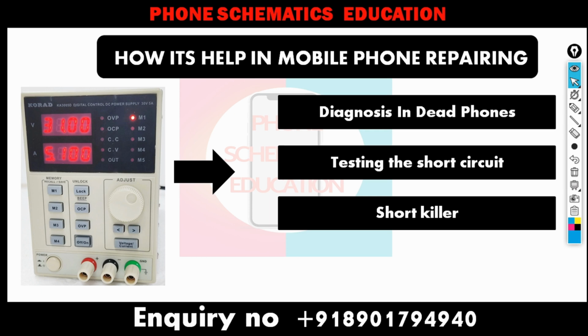A DC power supply is also used as a short killer. Through a DC power supply you can find which component or which IC is shorted on a motherboard, with the rosin method or IPA, or you can say thinner method. It is also used for removing the short.